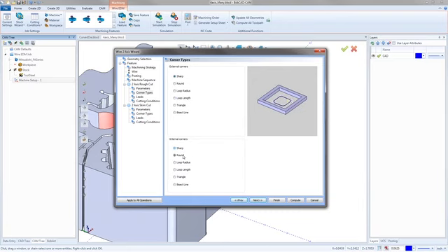The internal corners would probably cut a radius in the corner because it has to. If it's cutting an arc for the cut and not making a 90-degree turn, it should leave a rounded corner in there. But it's not intentionally leaving it. It's not even asking what size radius. That's how you know it's not doing what you might immediately think it's going to do. When we say round, if we were truly trying to round all the corners and make radiuses, it would ask what size radius we want. This is just changing how the wire, or if the milling has this as well, how the tool goes around that corner. So I'm going to leave them on sharp and then hit next.